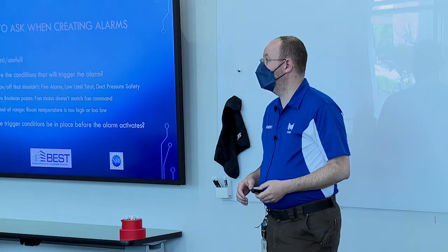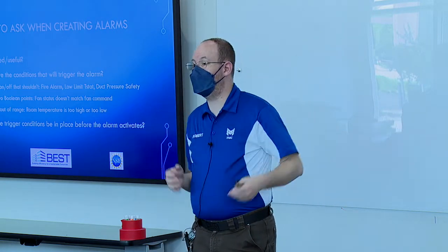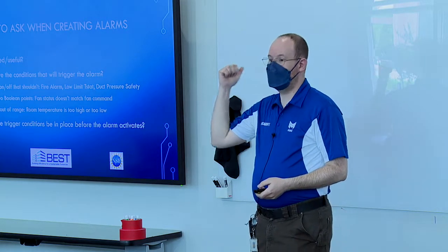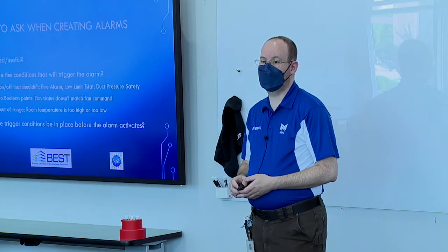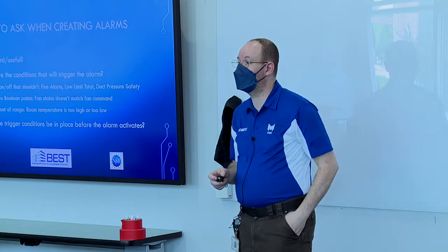They're safeties. Sometimes we also have to look at two different digital points. We commanded the pump on. Status says it's not on. Well, I'm going to assume the pump's broken. I've got to go look at it.